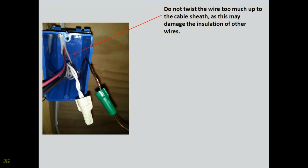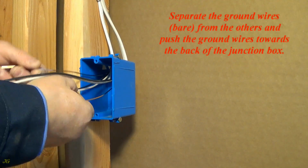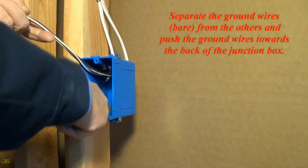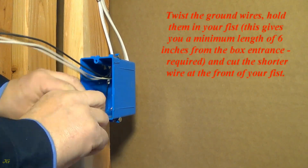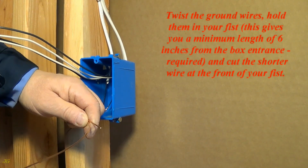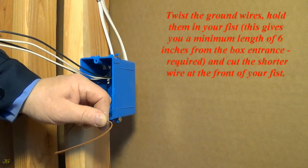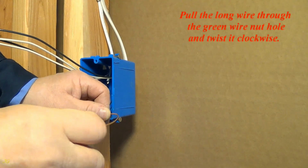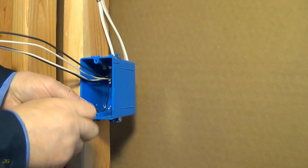Do not twist the wire too much up to the cable sheath, as this may damage the insulation of other wires. Separate the ground wires, bare, from the others and push the ground wires towards the back of the junction box. Twist the ground wires. Hold them in your fist. This gives you a minimum length of 6 inches from the box entrance, required, and cut the shorter wire at the front of your fist. Pull the long wire through the green wire nut hole and twist it clockwise.